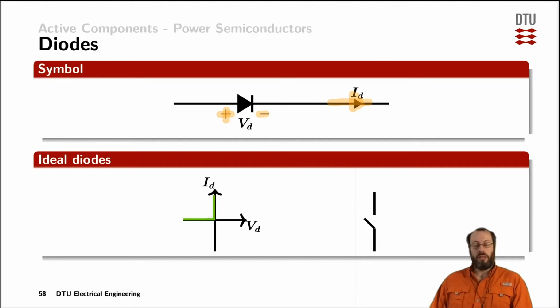However, if you decide to define the voltage or the current in the other direction, this is a matter of taste. But as soon as you have defined the potentials and the currents with their directions, you cannot change them anymore during your calculations. If you would change them in the middle of your calculations, you would actually get wrong results. So as soon as you have defined the direction of the voltage, you need to stick to it.